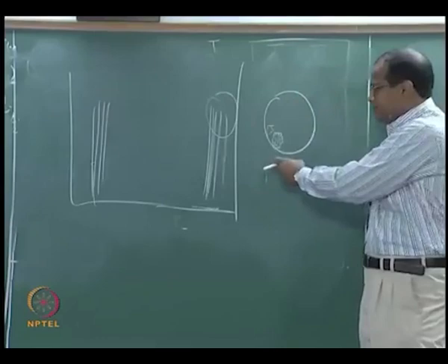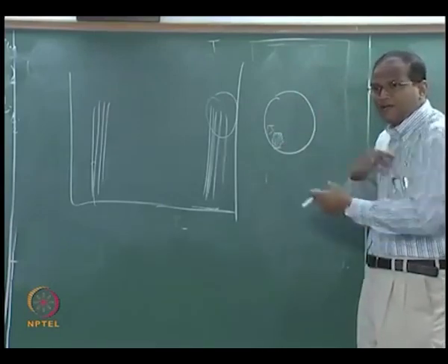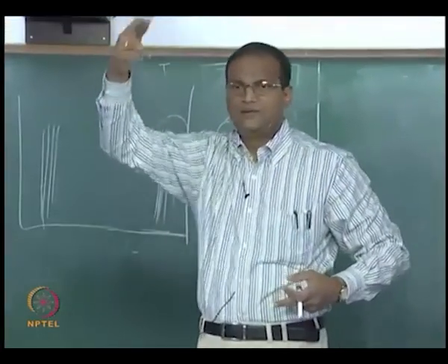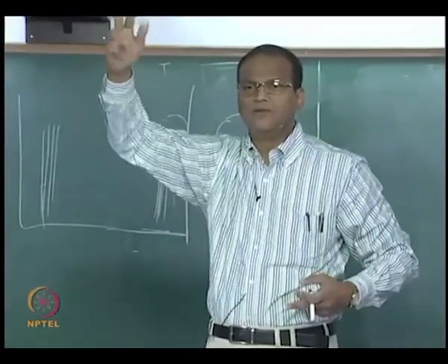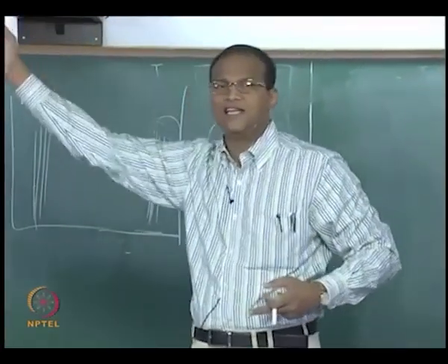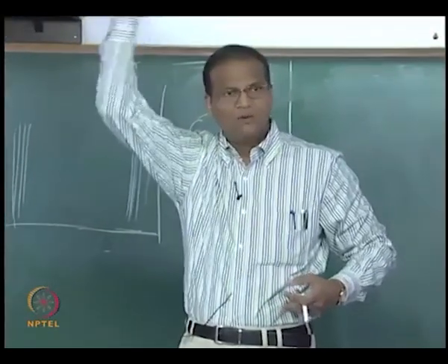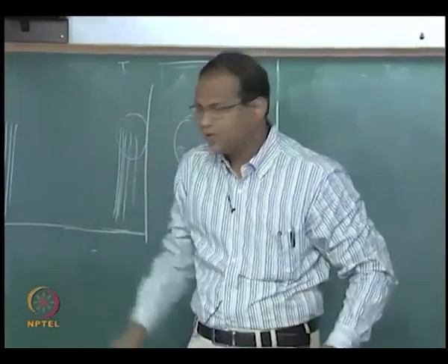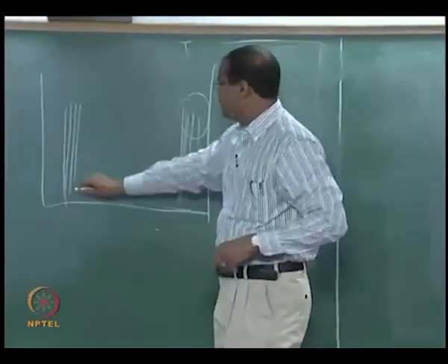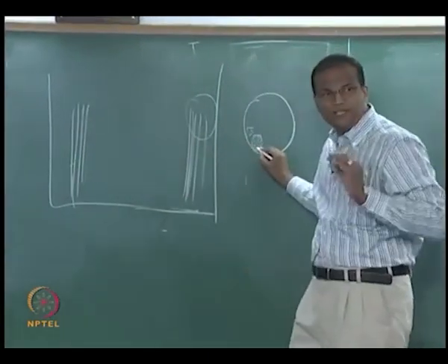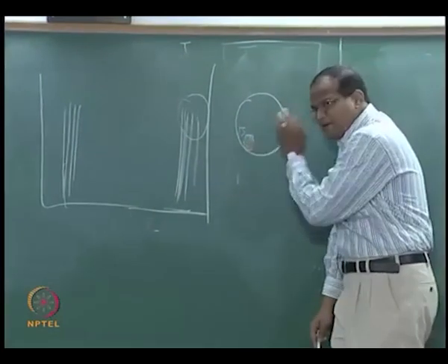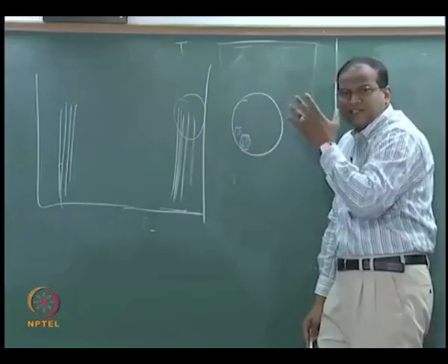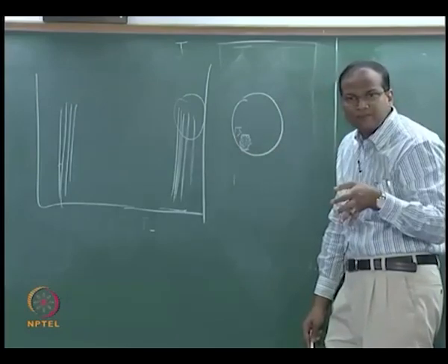Bottom to top the sodium will flow, it will pick up the heat, then it will go to a heat exchanger, then there is a secondary heat exchanger where secondary sodium will pick up the heat from the primary sodium, it will get heated, then at the third stage this sodium will transfer the heat to the water, water will become steam and then it becomes a regular Rankine cycle. Now this pumping of sodium is the primary place where the fission heat is taken away by the sodium. So this heat transfer process is accomplished by the sodium pump.